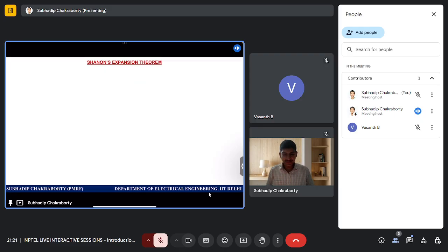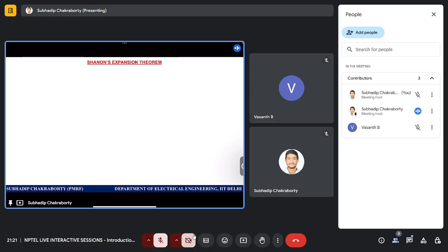And you have Shannon's expansion theorem, which is useful for Karnaugh maps for reducing higher order functions into simple smaller order functions. Now, why is it useful? If you want to find the Boolean expression for a large number of literals, more than 4, then using Shannon's theorem, if it is a function of 4 variables, you can write it by taking one variable out: A dot function of 1, put 1 in place of A, and then write it as a sum of products, or A bar dot function of 0, put 0 in place of A, and then BCD.